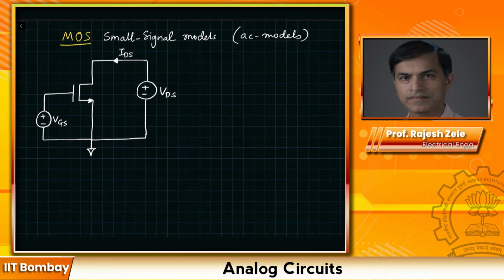We like to use the transistor in saturation region. So what is really going on in saturation region, as we saw earlier? If I change the gate to source voltage a small amount, then we see a change in the drain to source current. Now this is very similar to what we saw in the bipolar transistor, where we changed the base to emitter junction voltage and you saw a huge change in the collector current. So something similar is happening here.